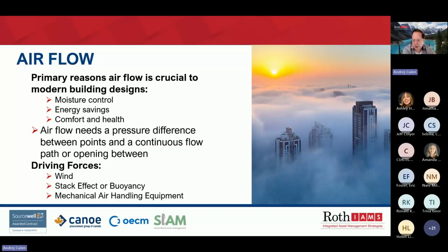And finally, it's for comfort and health. Cold drafts and the excessively dry wintertime air that results from excessive air leakage directly affect human comfort. Wind-cooled portions of the interior of the enclosure promote condensation, which supports biological growth, which in turn affects indoor air quality.